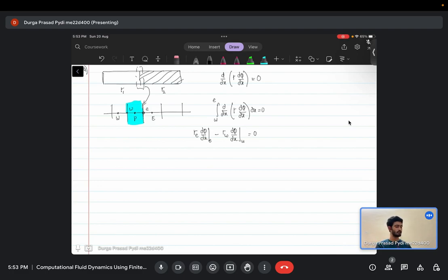The question now is, gamma west is fairly straightforward. Everything towards this side has diffusion of gamma 1 and everything towards this side has the diffusion of gamma 2. So gamma w on the west face, on this particular face, is equal to gamma 1. So that is fairly straightforward. The question is, what is the value of gamma e that we should take? If you took towards the left, it is gamma 1, and if you took towards the right, essentially you have a function which is discontinuous at that particular phase. So what value do we have to take for gamma?